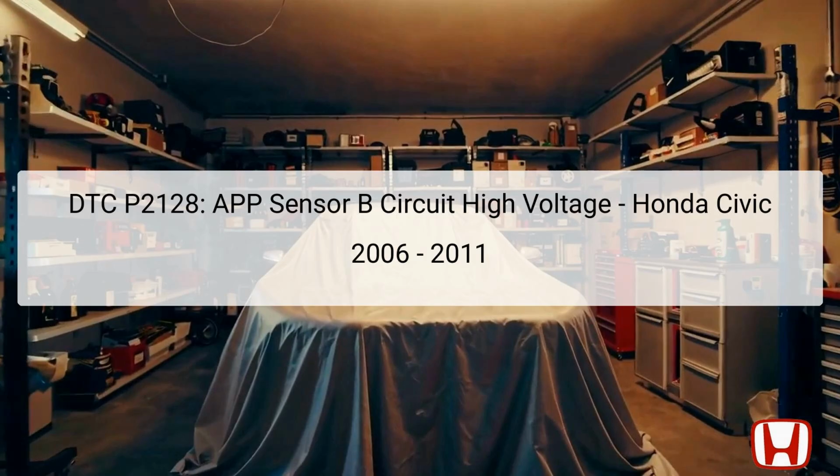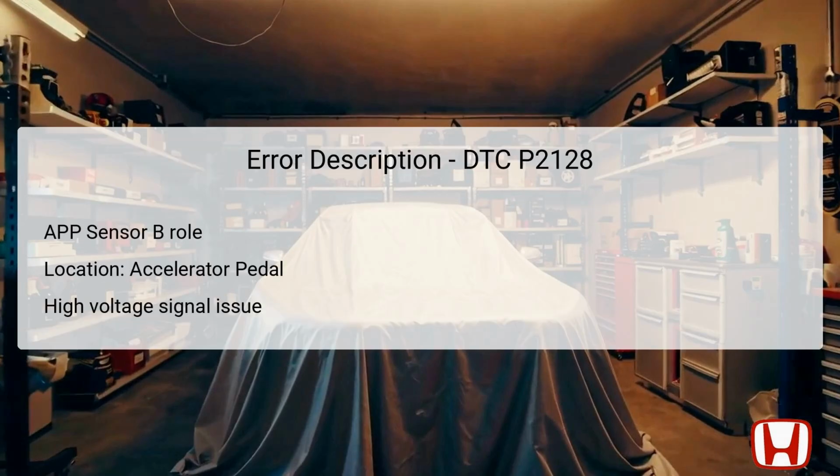Before beginning the troubleshooting process, ensure you record any freeze data and review the general troubleshooting information available within your diagnostic tool. The error code P2128 identifies a problem with APP sensor B, specifically indicating a high voltage circuit issue. The APP sensor plays a significant role in determining the accelerator pedal position and is essential for the vehicle's throttle control. This sensor provides real-time data to the engine control module, allowing for precise adjustments to engine output based on